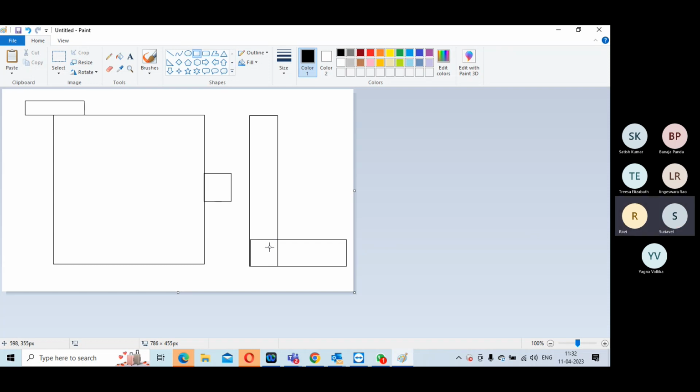Irrespective, let me tell you, macros will only talk to one particular module or certain things. You should never place a macro at a common point, just like you are trying to isolate. You will try and place memory there, but this is the logic which has to communicate. If you block this common area, then there's no route possible and no cell position possible.